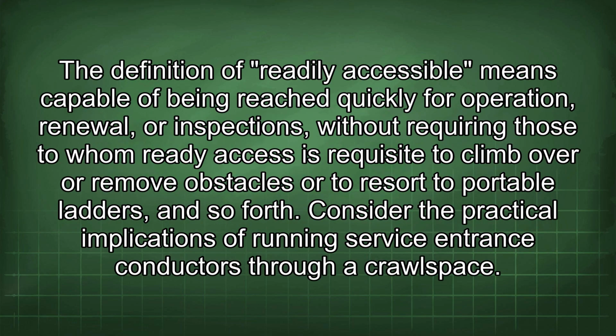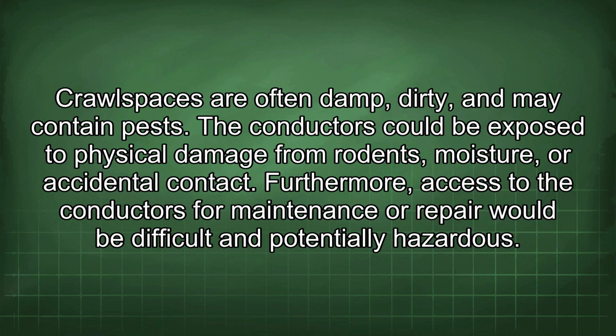The definition of readily accessible means capable of being reached quickly for operation, renewal, or inspections without requiring those to whom ready access is requisite to climb over or remove obstacles or to resort to portable ladders, and so forth. Consider the practical implications of running service entrance conductors through a crawl space. Crawl spaces are often damp, dirty, and may contain pests. The conductors could be exposed to physical damage from rodents, moisture, or accidental contact. Furthermore, access to the conductors for maintenance or repair would be difficult and potentially hazardous.